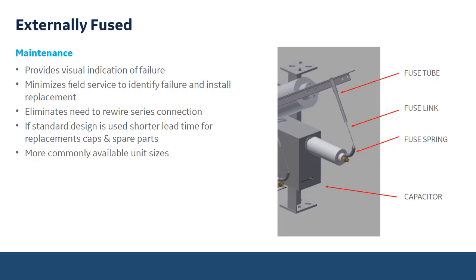Some of the benefits of the externally fused is it eliminates the need to rewire series connection. So if it is a fuseless capacitor and you have multiple units in series, if one goes, the maintenance team will be required to remove the old and re-terminate the connections there.